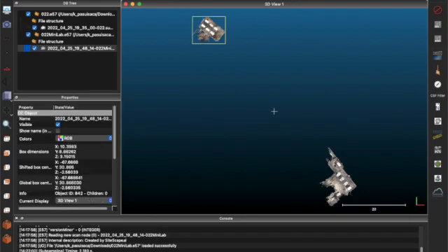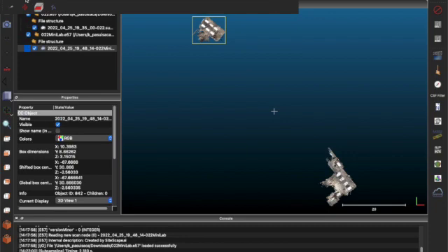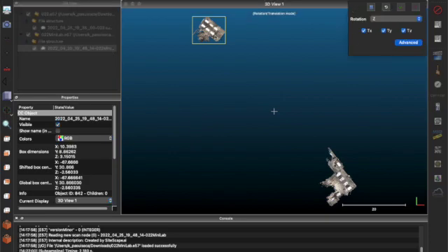and click on the scan I'm gonna be rotating and translating to merge. So we're gonna use the rotation translation tool, and with the right click of the mouse, we're gonna go ahead and drag it next to the scan. So I kind of like to play with one axis at a time. Right now it's at Z, and using the left click on the mouse, we're gonna go ahead and just drag it to try to match it with the other scan.